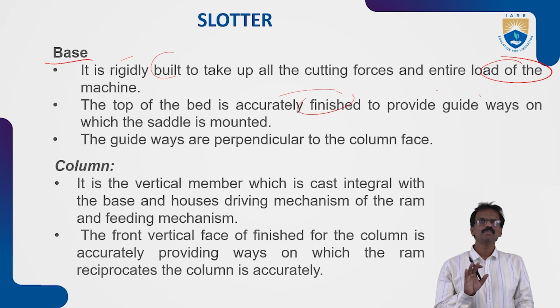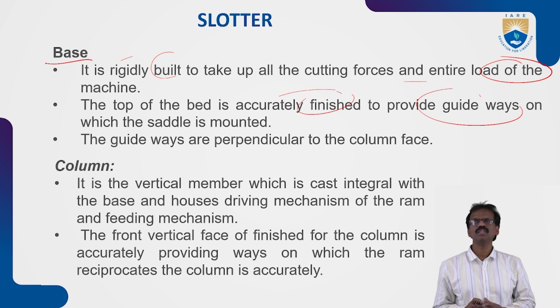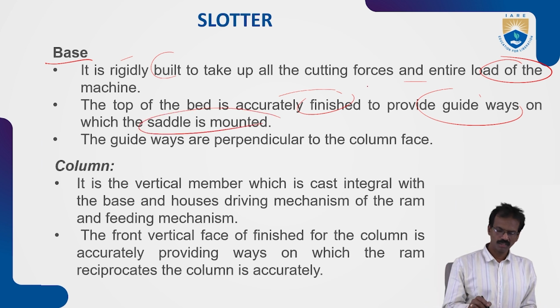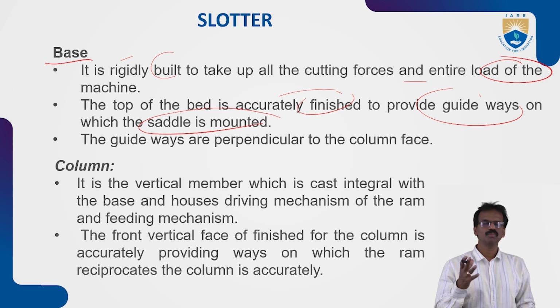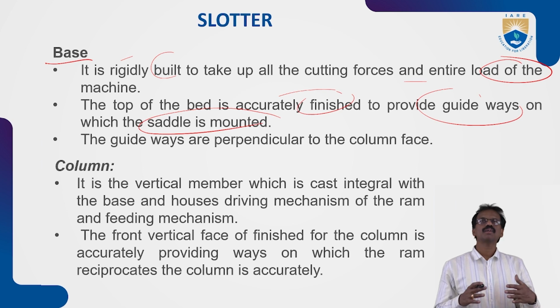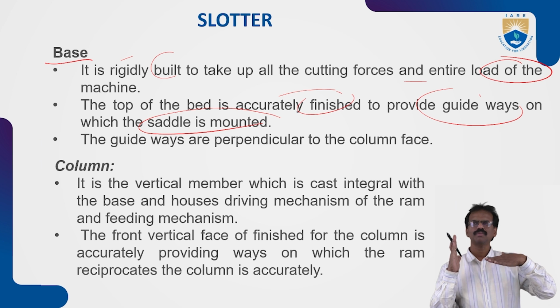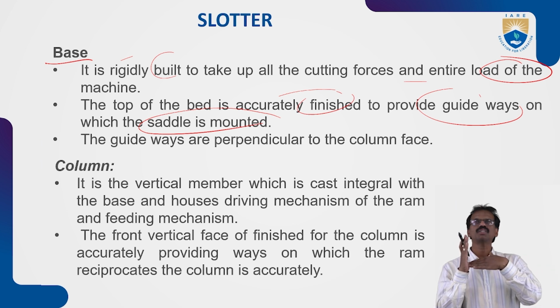The top of the bed is accurately finished to provide the guideways. These guideways are very important. On these guideways, the saddle will move towards the column and away from the column. The guideways are perpendicular to the column face. So on these guideways, the saddle will move towards the column and away from the column. So it provides the longitudinal movement of the workpiece.